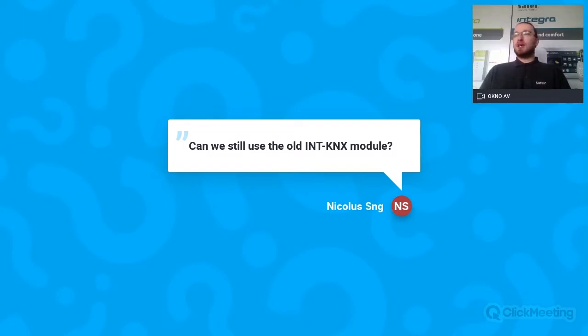The big difference is that INT-KNX requires an additional BTM module between the INT-KNX module and the KNX to convert the bus. INT-KNX-2 has it already on board, so it's easier and gives you a few more possibilities, also for installation. But yes, you can use almost the same idea with the INT-KNX-1.